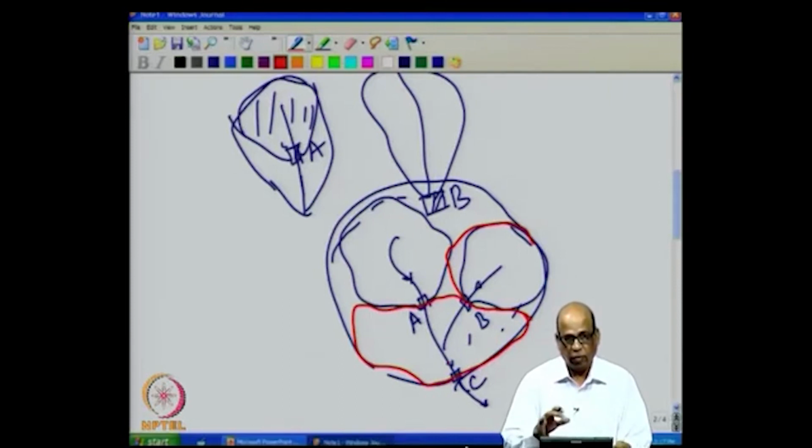If your recorded data is correct, then it means one of these two things. One is that the precipitation values are much higher here, or that the hydrologic characteristics are much different compared to these other two catchments, and therefore, it points to a non-homogeneity of this catchment compared to the other two catchments.